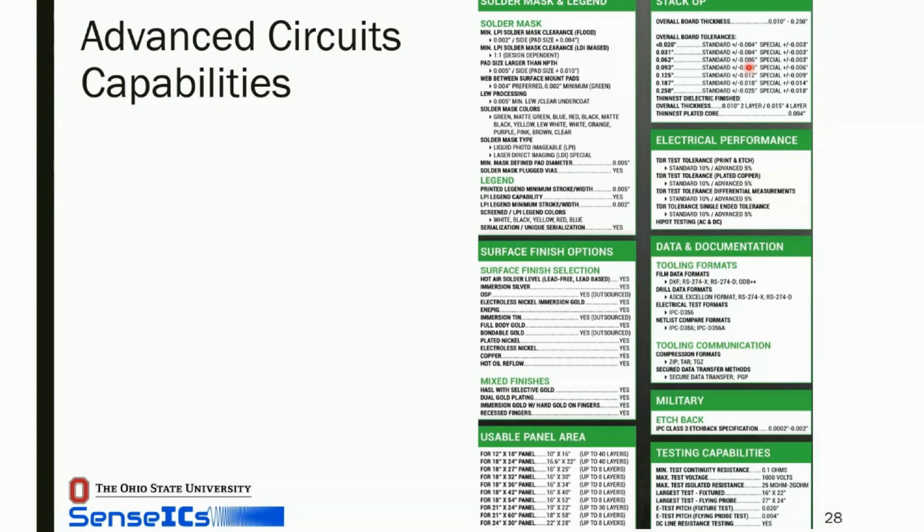Gus, let's have it. Right, so I think it's a great question. Yes, everything that is exposed, once you do one of the plating techniques, so the hot air solder leveling or the ENIG that we talked about, every exposed copper will be covered with that material. So yes, the answer is yes. Now, the PCB vendor, if you wanted to do the thing that the PhD student talked about, that you wanted to have exposed copper and nothing on top, they probably could mask it off for you if you wanted that. But I've never had a reason to attempt that, but I think it's probably possible.